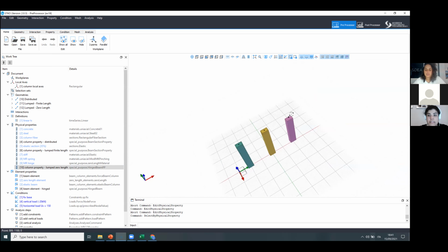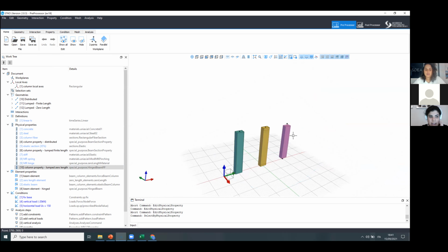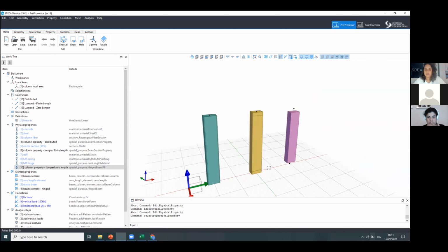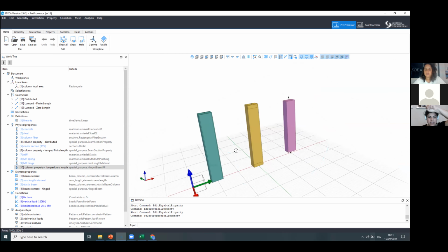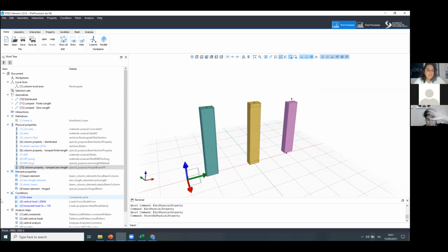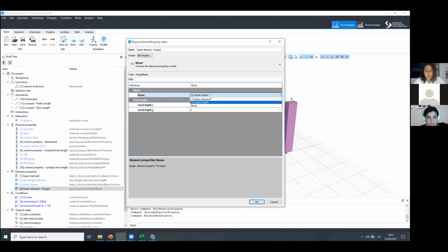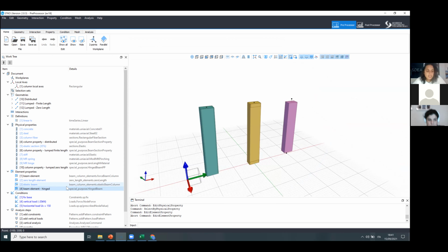Oh, no, this was because I wasn't seeing where the elastic property was, because we were saying one part is elastic because we collapse everything in the extremities. So I was not saying something correct before, because you do need an elastic beam column element for your beam, and also a zero length element. So the hinge beam here is created the same.